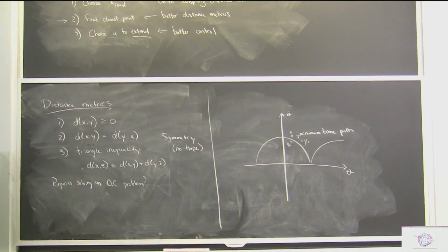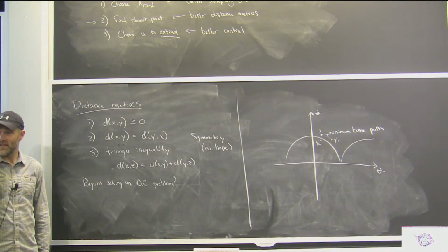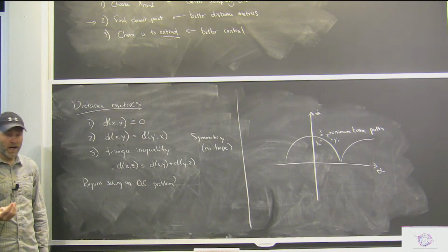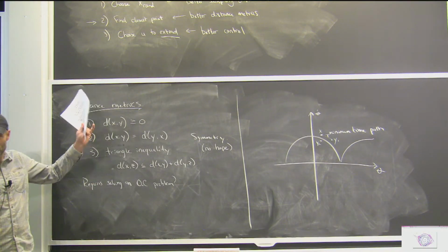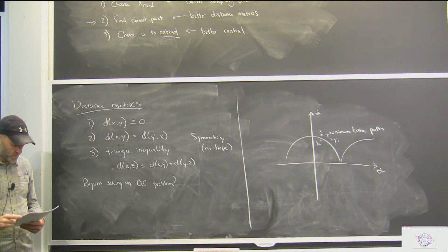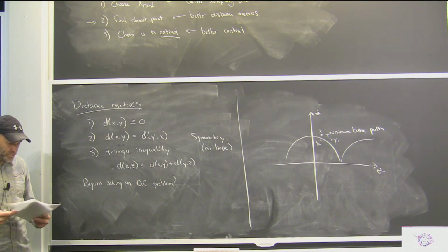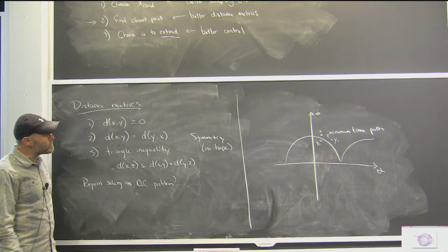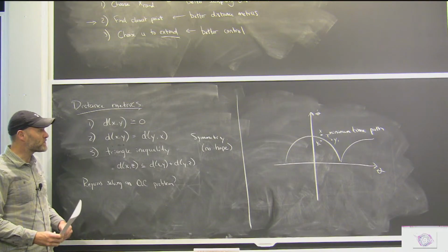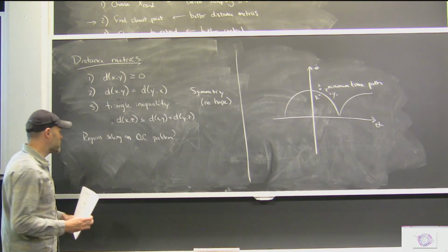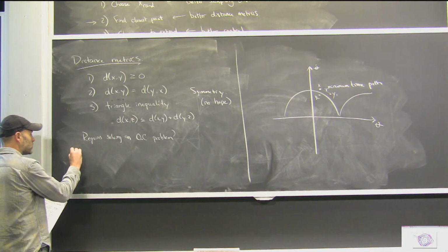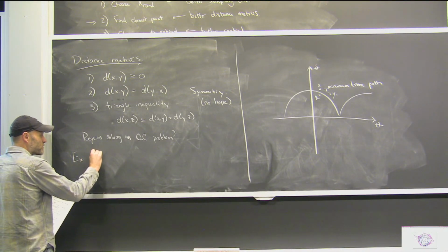So the trick is, if we have to solve the entire optimal control problem in order to get a good distance metric, is there some sense in which approximate distance metrics or approximate solutions to the optimal control problem are more obtainable than solving the big hard optimization? Because otherwise, if we could just solve the optimal control problem, we would have been done, right? Okay, so here's the favorite example. I think that is a very satisfying solution to this, for instance, UAVs flying around obstacles. It is from Emilio Frazzoli's thesis, actually.